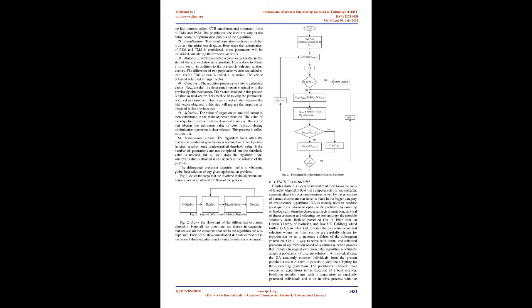Time multiplier setting: the time of operation of the relay can be set at a desired value. In an induction disk type relay, the angular distance by which the moving part of the relay travels for closing the contacts can be adjusted to different operating times. There are 10 steps in which time can be set. The term time multiplier setting, TMS, is used for these steps of time settings. The values of TMS are 0.1, 0.2, up to 0.9, 1.